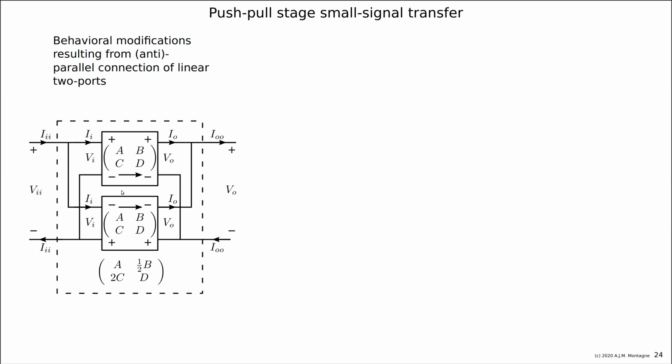We have, again, the two ports and the transmission one matrix. That is our favorite method of representing amplifiers, the two-port parameters. And now we see that we have not B doubled, but we have half the value. So the gain from voltage to current is doubled. And that is what we have seen in the previous picture, because this is 1 over the transadmittance. And C is doubled.